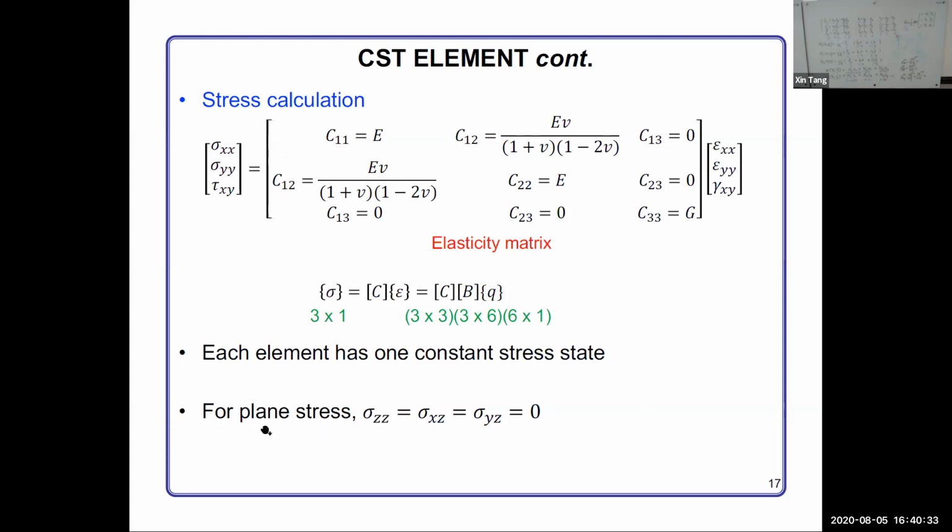You may also remember the plane strain condition. These are two very important plane conditions, 2D conditions, in mechanics. Plane stress is for when the plane is very thin, so all the stress is in the plane, not off the plane. Plane strain is for when the body is really thick. In the Z direction, because it's too thick, you cannot have displacement. It is constrained, like it is clamped there.